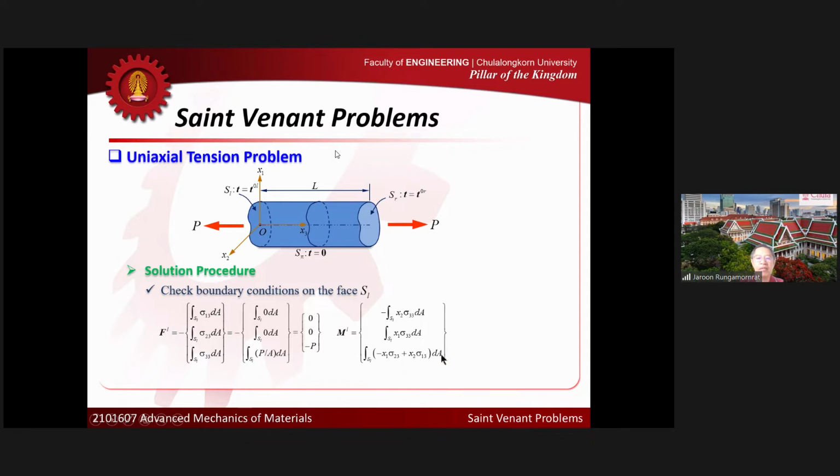We can do exactly the same thing for the net moments. We plug the components of stress that we got before into this formula. So now we can get the net moments generated by the stress field that we have. Sigma 3 3 is constant, so we can plug it in here.